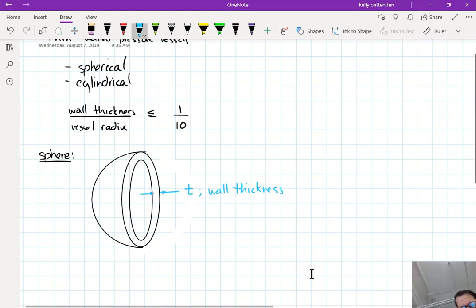And so we have this pressure inside here. I'm going to draw it like it's a solid, but obviously it's some kind of liquid, air or water or whatever inside here that's pressurized. And I've just sliced through it. And there's this pressure that I'll just lump into a single force P. So this force P is trying to explode the pressure vessel.